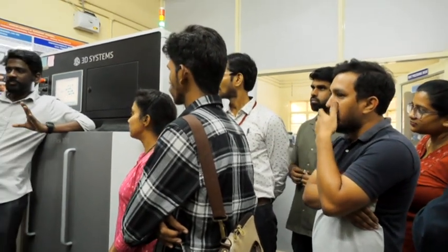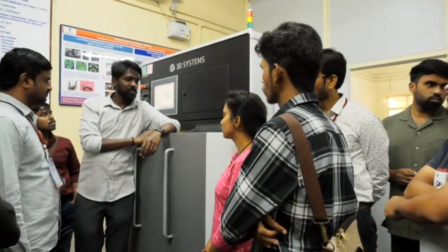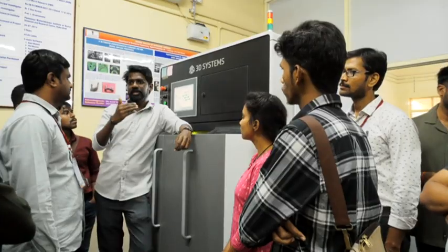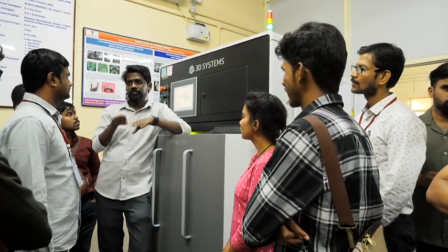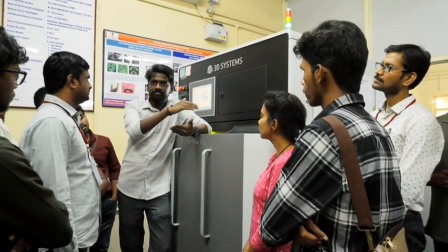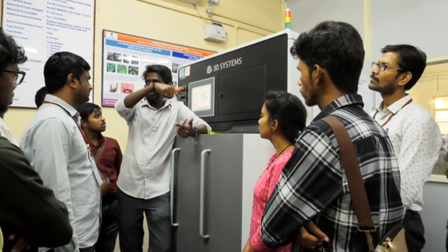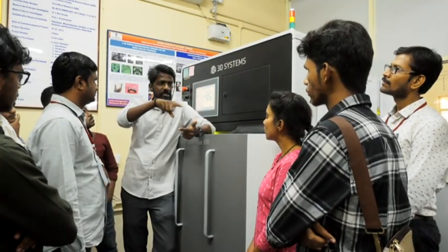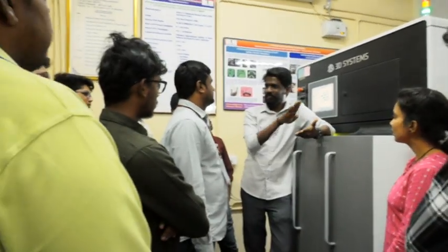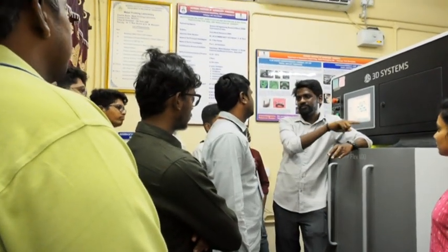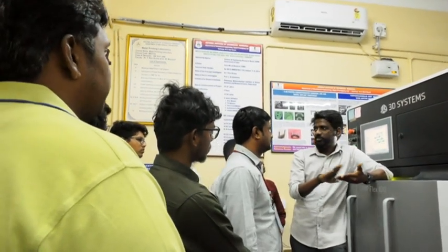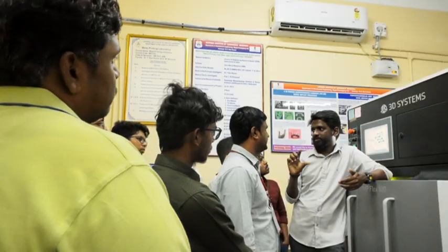After giving the process parameters, the machine will use a galvanometer for the laser and pneumatics to move the supply piston up and down. First of all, the roller will spread the powder on the substrate. Then the laser will melt the powder particles. It will spread one layer, then the next layer, stacking of two-dimensional layers, same principle. Whatever you applied in AM, you can get here also. Finally you get the 3D component.